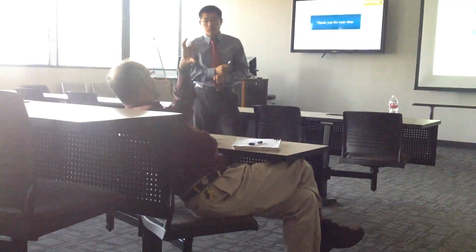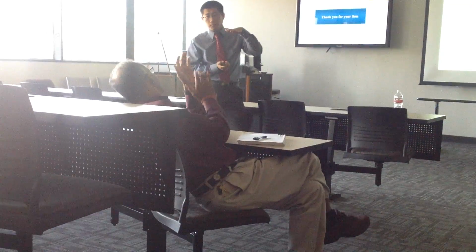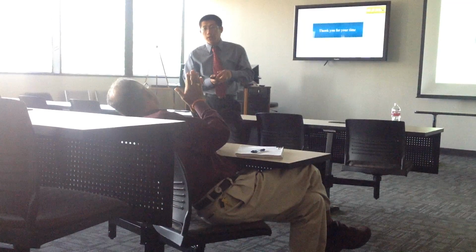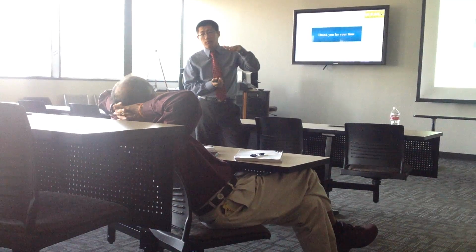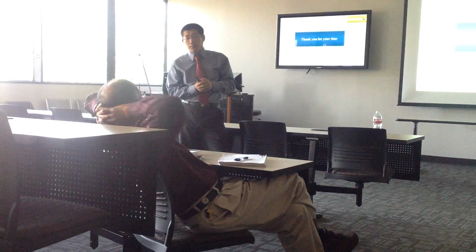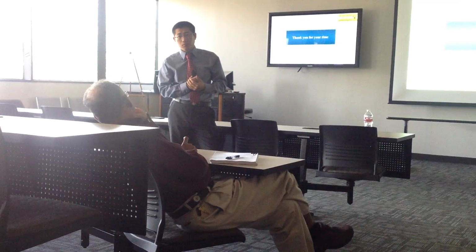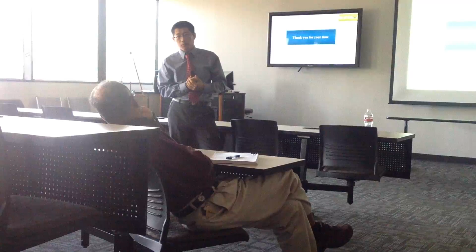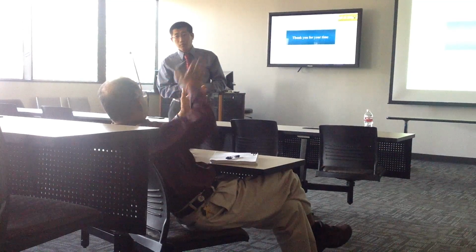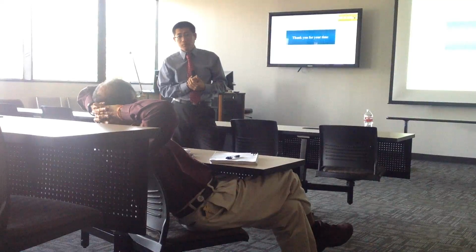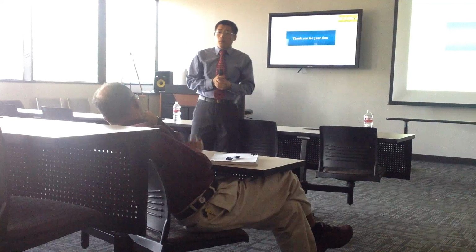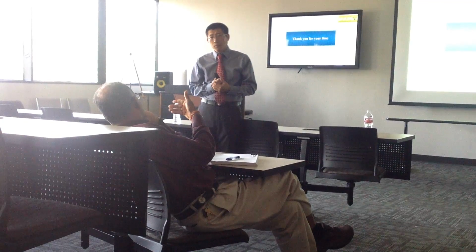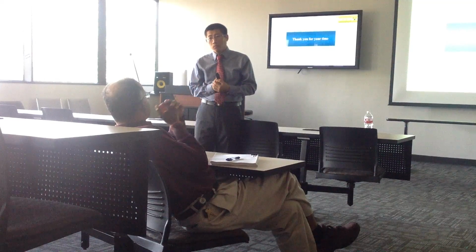So if I'm looking at net benefit, then the higher the Y plus value, the less the simulation time. Right? Yeah, you can see that. So I'm saving simulation time by increasing the grid size. Yes. So is that significant enough between going from a Y plus value of 30 to 150? Of course, that's a big jump. But is that significant savings in simulation time? Or what I meant is, is it worth increasing the grid size?